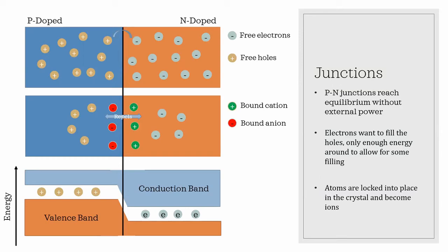The n-doped side has a bunch of electrons left that could move, but the conduction band on the p-doped side is higher than the n-doped side. And all the electrons with enough energy have already crossed over, so we've stopped our flow of current without adding more energy into it. You can see from the plot on the bottom that the conduction band and the valence band switch kind of magnitudes at the boundary and the interface region.